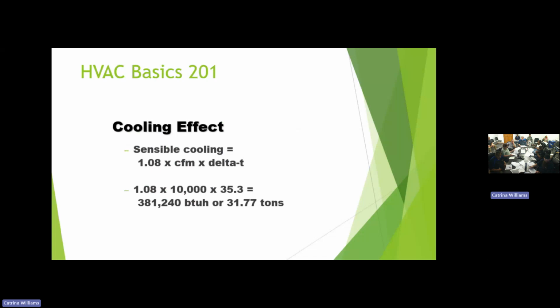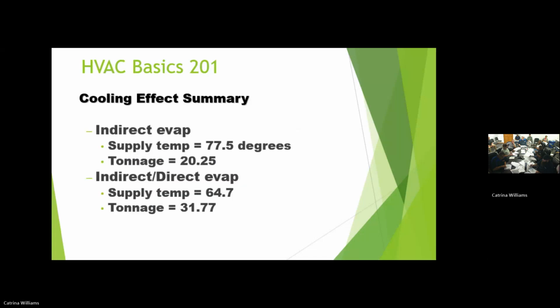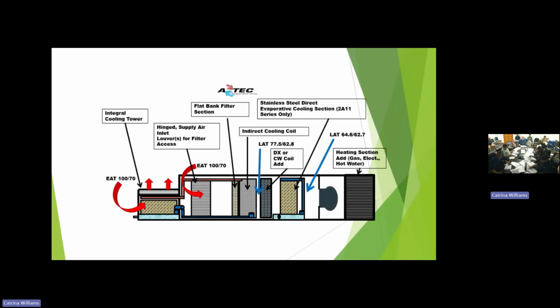Well, I think they're around 3,000 apiece that we're moving. I bet you got close to 10,000 CFM going through your paint booth. So 10 of those. It's probably replacing the air that the paint booth would exhaust out. So there you see the summary with the 31.77 tons.